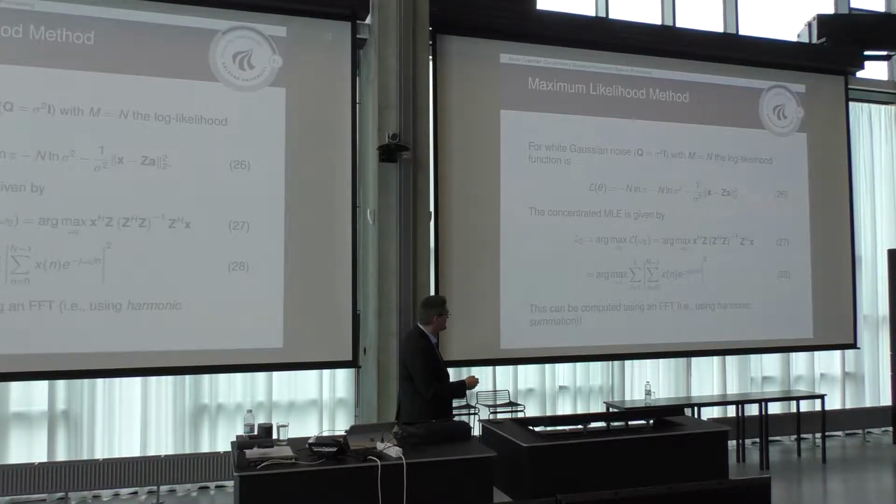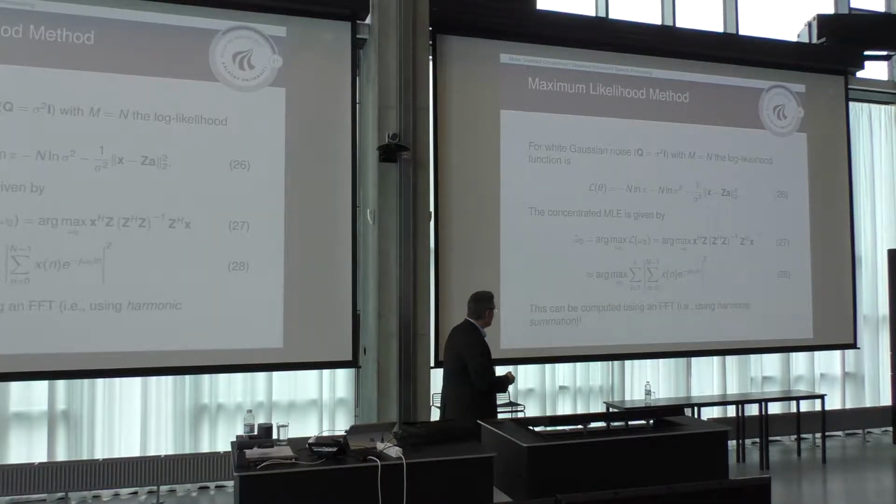Well, if you check this out, you can see that this is actually just a Fourier transform of X evaluated at the fundamental frequency times L. So basically, you should measure the power in the spectrum where the harmonics would be for a certain candidate fundamental frequency, and you add that up, and when you get the most energy, you have your estimate. Really simple.